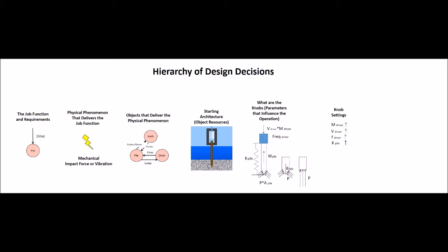We could also increase the stiffness of the pile. This would be done by changing the pile structure and materials. This has its own problems and contradictions, mostly related to cost. We could decrease the pile diameter. This reduces the area that the ground pressure operates and allows the pile to go in much easier. Again, this has some very obvious problems and contradictions related to pile breakage and the ability to support a heavy structure. We could decrease the mass of the pile by changing its structure and materials. This has problems and conditions related to cost and durability of the piles.